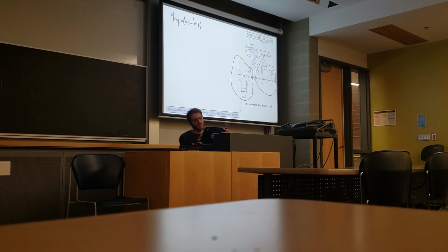So previously we wanted to go from 4 to 6 directly. Now we go from 5 to 6. So the amount that we save is 5 to 4. It's like 4, 5, 6. Right? We wanted to go to here. Now we go from 5 to 6. So this is the amount that we save. Right? So basically Q regeneration means the amount of energy that we save, which is H5 minus H4.